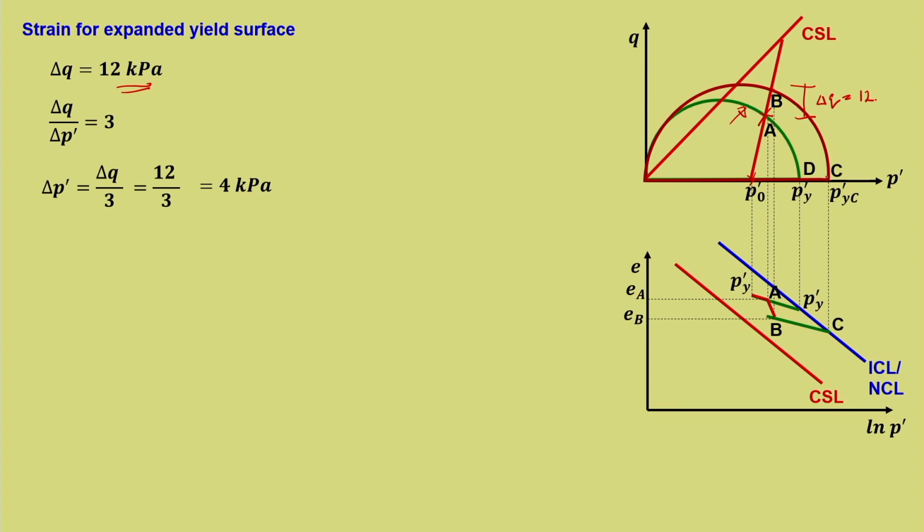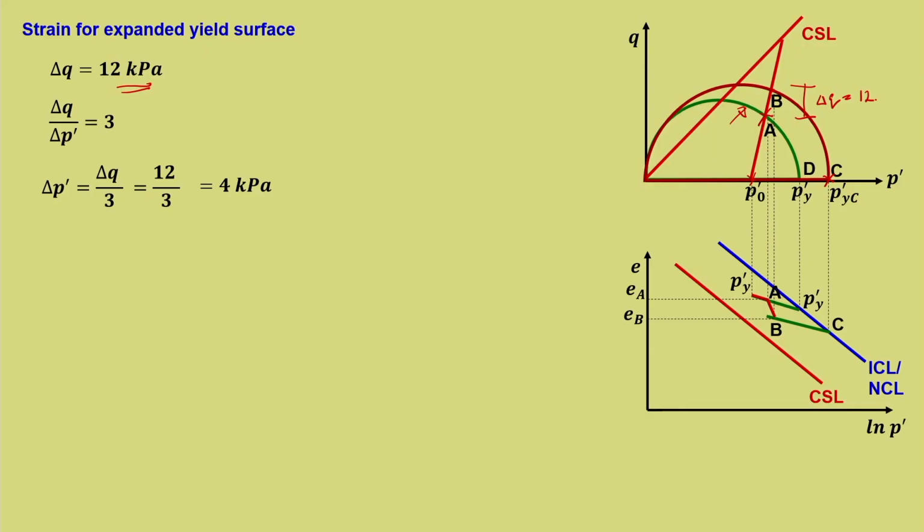And now we need to find out, for this particular point, what is the maximum yield stress corresponding to the expanded yield curve. Remember, the soil sample has not failed, it is intermittent. So, this is an intermittent yield circle. The same thing is shown, please refer back to the lecture for more explanation.